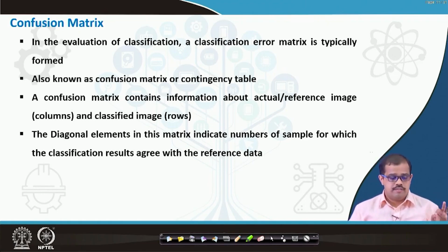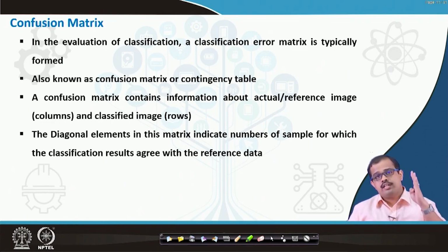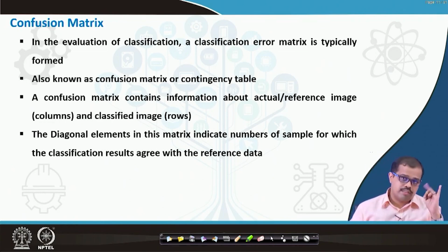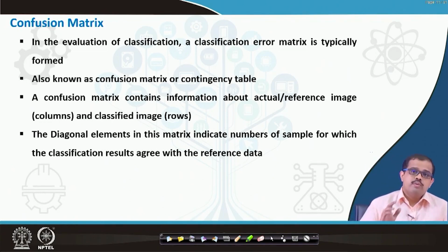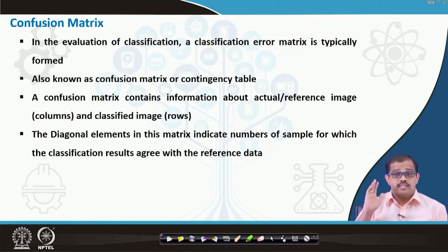So now if I have created 4 classes, let us say urban, water, vegetation, others. Okay, so you will have 2 images with the same reference details. Okay, coordinate system is the same, datum is the same, and the projection details are the same. One is a user map which you have created using your field data collection, with signature collection over the heterogeneous region, whereas the other one is a reference map which is considered to be almost accurate.